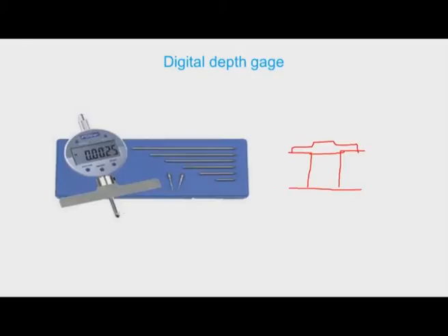And then we have to make the rod move in, and that carbide tip will contact the bottom, and then this indicator will directly give the reading. And then extendable rods are also available depending upon the depth of hole or the height of the workpieces. We can select appropriate extension rods, and then we can fit them and use them.